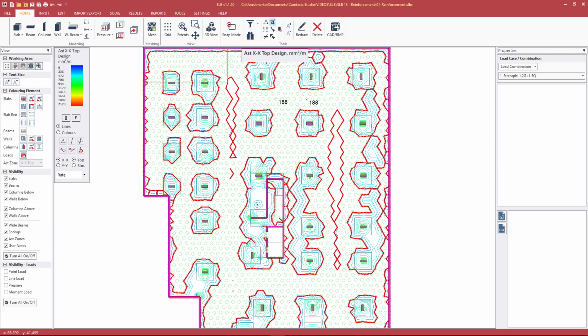If we were to see blue dots, what blue dots would indicate is that the steel there has been increased to satisfy crack control for flexure requirements. So this is steel that is added additionally in the tensile zone, because that's where flexural cracks will occur. For shrinkage and temperature effects, the cracks extend through the entire section of the slab.